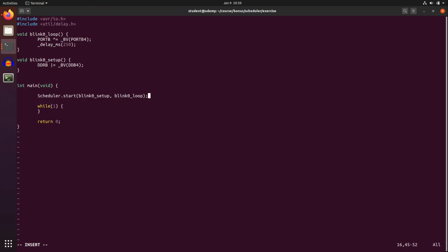The thing is, the functionality that I would like to have in the end are 3 different LEDs blinking independent of each other. And I would like to avoid to clutter my source code with a lot of tiny little functions. Therefore, instead of implementing 3 different setup functions, I just define DDRB to be an output right here, and that too only once. And then I can skip implementing this. Or DDB3 or DDB2.